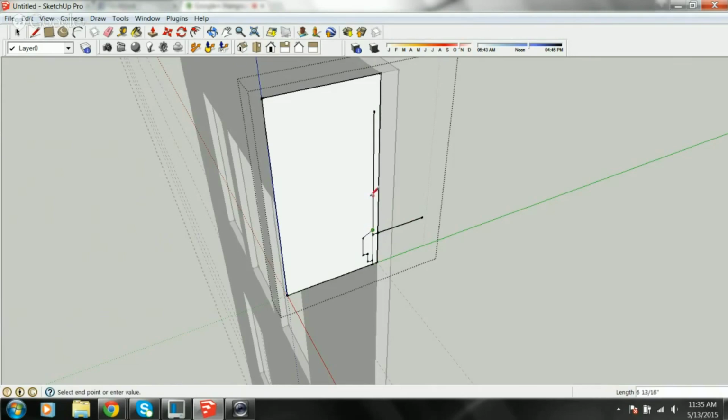I've got that built. Let's come up 12 inches because that's what I saved for this middle section here. You see how that little piece popped up. Now I've got an endpoint to click that's 12 inches off the bottom. But I'll measure it just to make sure I didn't mess something up. Look in the bottom right-hand corner. It says 1 foot at the end of my tape measure. Okay. Hit the space bar to get out of the tape measure command.